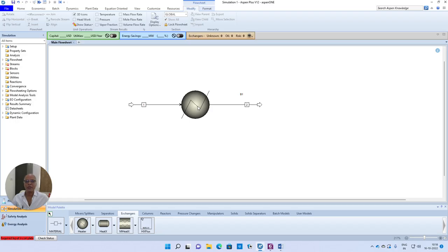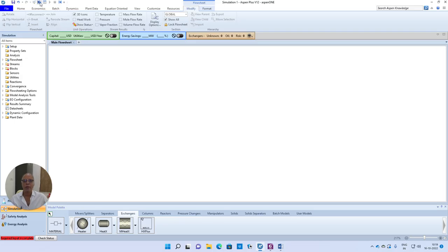Normally, we will be using such simplified models for performing preliminary mass and energy balances. Once the mass and energy balances come to a convergent solution, probably at a later stage, you can replace this unit with a unit or model which is capable of doing the design calculations. So don't try to make your simulation complex right in the beginning. That's the normal process that we'll be using. So let us go into the specification of the problem for this.